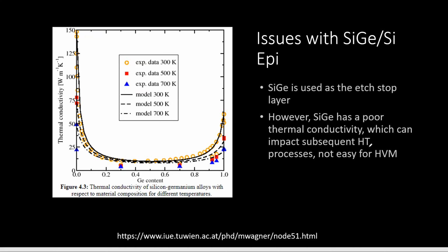Imagine if you put an insulation on top, the wafer cannot be cooled properly. You have to adjust your process. If you don't, oops, then your wafer is hotter than you think. When the temperature of the wafer is hotter than you think, using the same process, you definitely get different results. So it's not an easy thing to do. And there are many other high temperature processes that you need to adjust to compensate the CD. If you don't compensate, then your yield will definitely be low. So that's one thing everybody's working on.